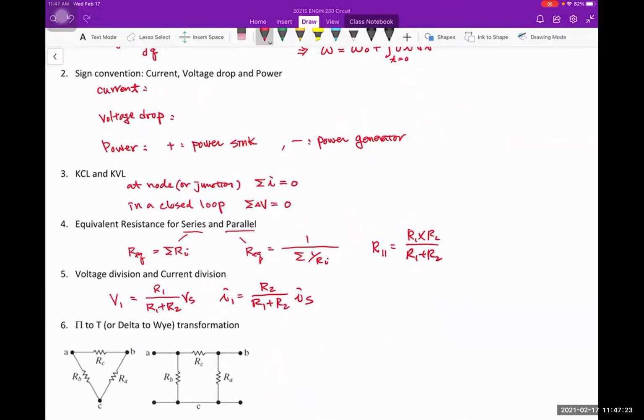so I was talking about the parallel and series resistor. I didn't give you the equation in the formula sheet, but I think you should know. In series, you just add them together. In parallel, you have this very easy equation to use, but this only works for two. So if you have two resistors in parallel, you can always use this equation to find a solution.